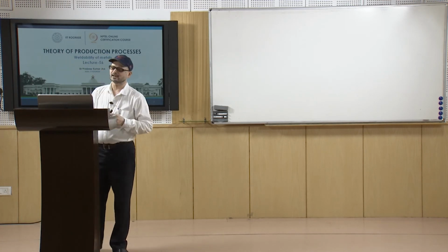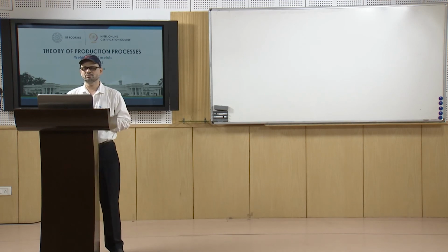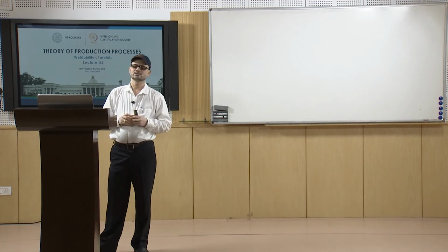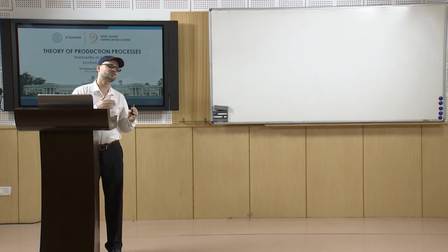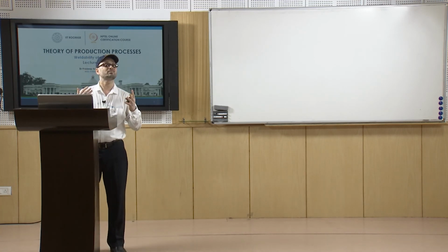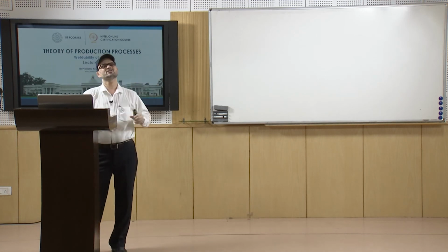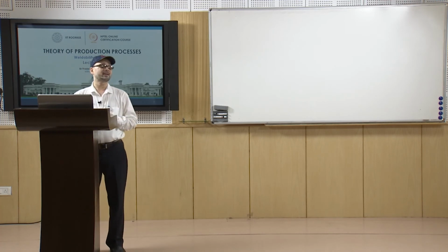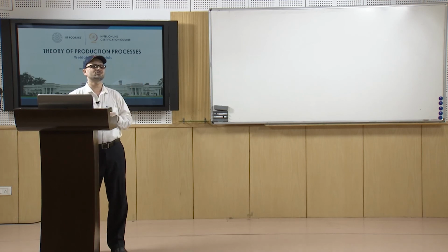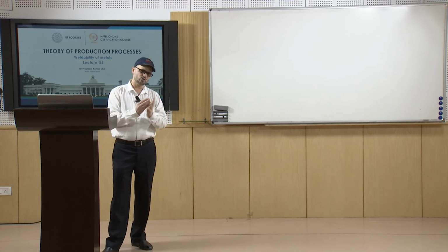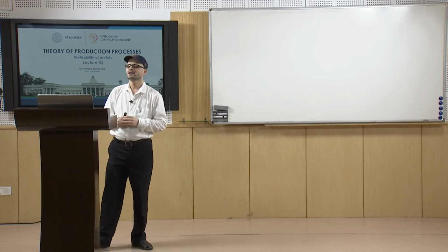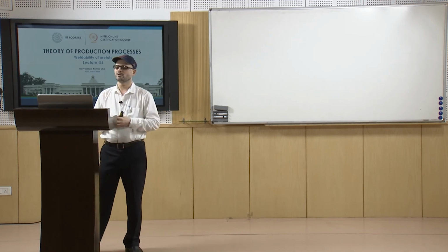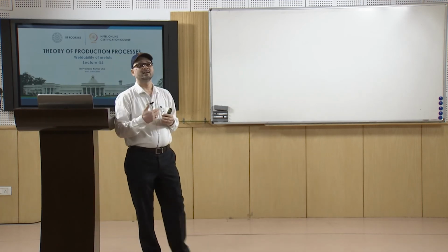Now, when we talk about the weldability test, they are classified as either theoretical test, simulated test, or you can have the actual welding tests. When we talk about the theoretical test, what we do there is that we have a number of notched bend specimens, and they will be austenitized at a certain temperature, suppose 1150 degrees centigrade, and then we cool at some calculated rates to duplicate this process so that you get the expected hardness of the HAZ, and then you try to bend the specimen through 10 to 20 degrees. So, if you are able to bend it, you say that it has a good weldability. Otherwise, you say that yes, weldability is poor. So, this is about the theoretical type of test which is carried out in the case of weldability.